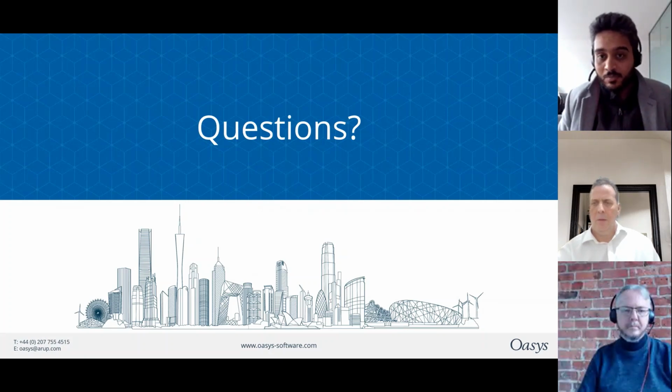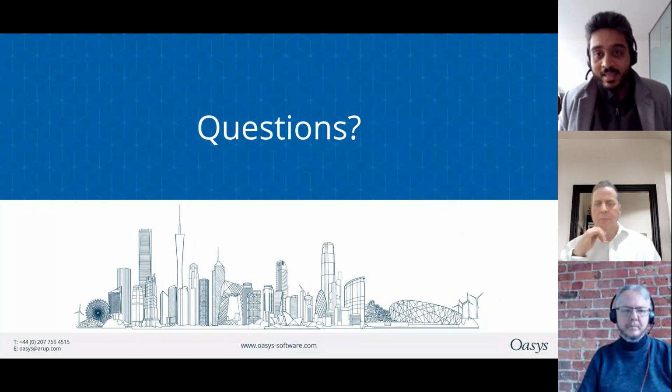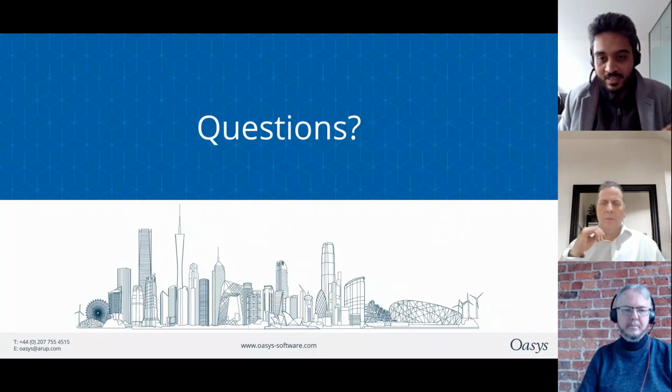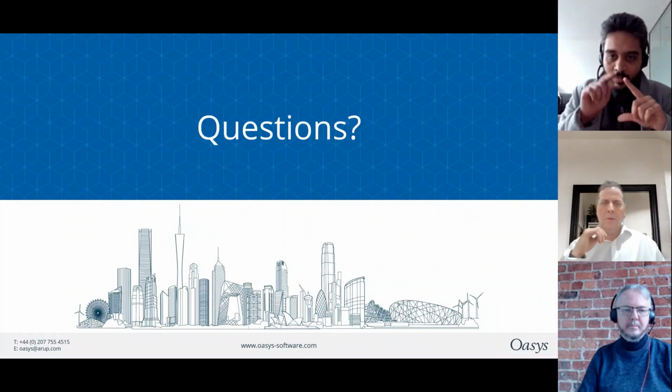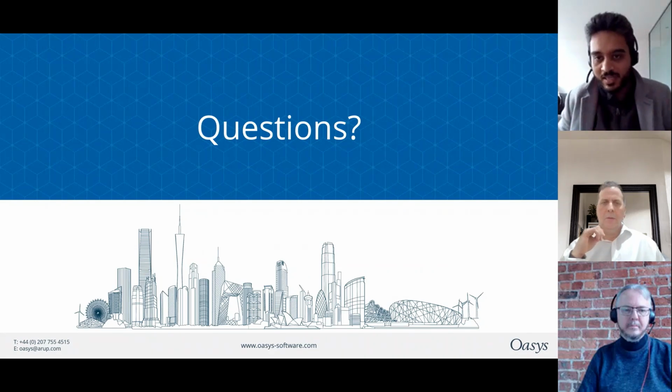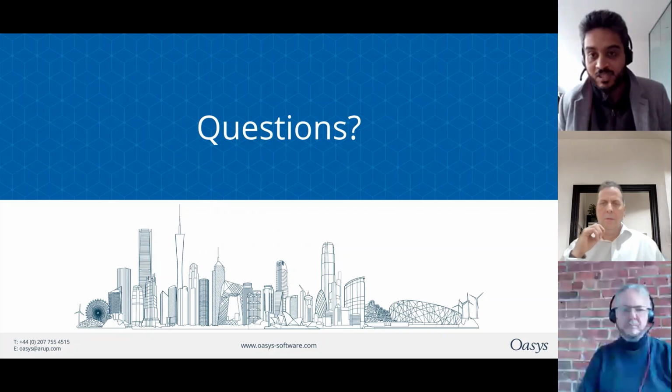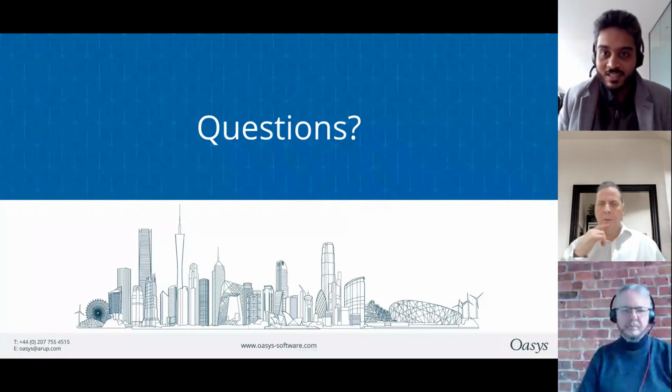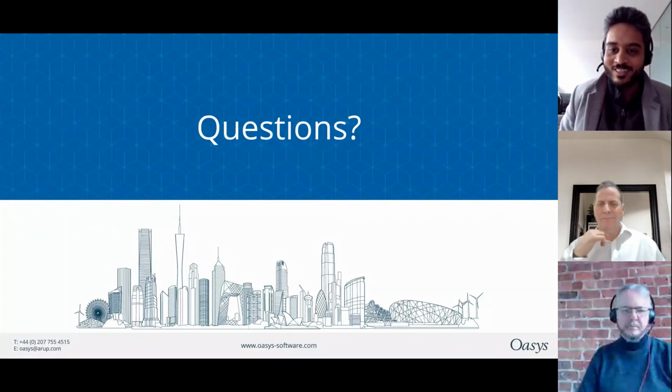And yes, you can model triangular elements or quadrilateral elements. Both shapes are possible. Even within triangle and quadrilateral elements, you can choose between linear elements, which in the case of a triangular element are made of 3 points, or you can choose a higher order element, which will have 6 nodes and have quadratic shape functions, for example. So yes, all your questions and more are possible.